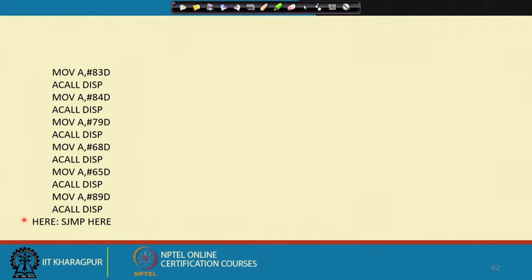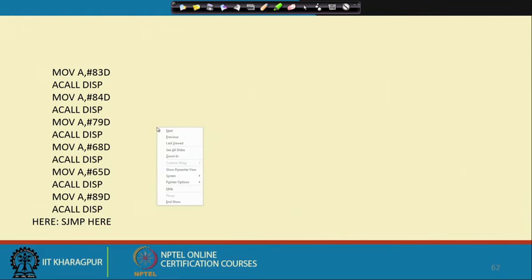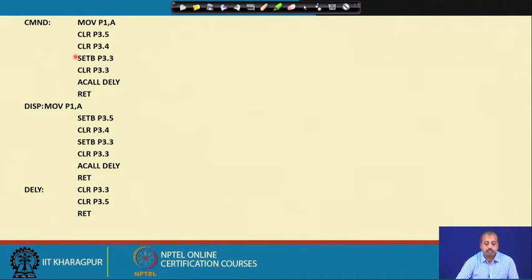And if you want to clear a cell, then for that purpose you have to write a new character onto that cell, or if you want to clear the display altogether, you can do that by the clear display type of command. So, this program ends with an infinite loop here, because nothing more serious needs to be done. So, this was the program for this command code part. The command code register is loaded with these values, these statements.